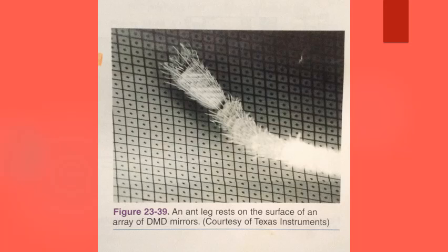The DMD technology is combined with a light source and lens to create a DLP system, in which each individual mirror corresponds to a digital signal that represents a single pixel in the image to be created on the television screen. The array of mirrors can be switched on and off over 1,000 times per second. The length of time each mirror is switched on and off is used to produce an array of light and dark spots on the target screen. Varying the amount of time each mirror changes from light to dark will produce a specific shade of gray on the screen.